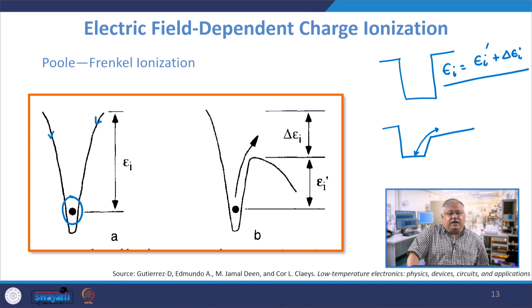So what I have effectively done is reduce the barrier potential, right. The barrier potential was very high in one case, now it has reduced to almost half of it, and therefore the probability for the electron to escape the barrier almost doubles, right, and therefore you will have a large amount of electrons available to you.